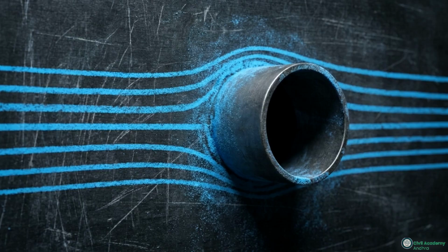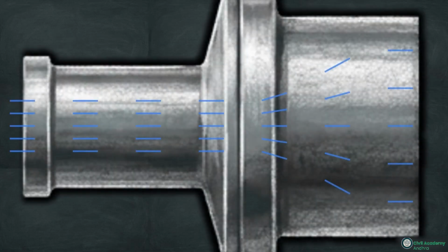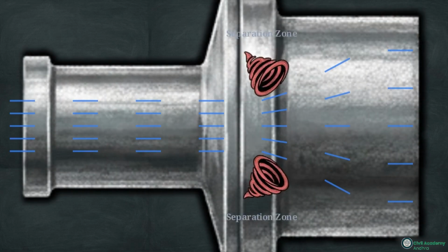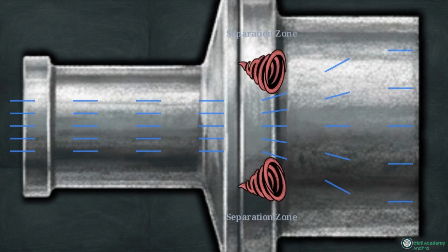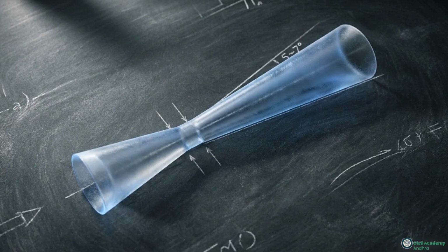Bernoulli's equation assumes a frictionless ideal fluid, which does not exist in the real world. Real fluids experience internal friction, and their momentum causes them to physically separate from the pipe walls when their velocity is suddenly manipulated by physical devices. To measure real-world flow, we bridge theoretical physics and empirical reality using device-specific geometric designs and mathematical coefficients. Engineers prioritize the venturimeter for high-pressure systems because it measures total flow while preserving nearly all the fluid's initial energy.